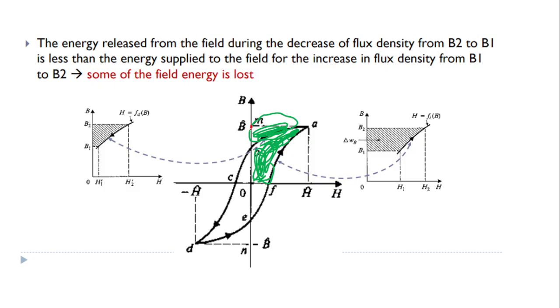So this piece on top here is the area bounded when you're going back down, right? So that's the red piece there. But when you're going up from here up to here is the green piece. See now? So if you subtract the red from the green piece, you'll get this piece inside the curve right here. And that area there is where the hysteresis loss will be.